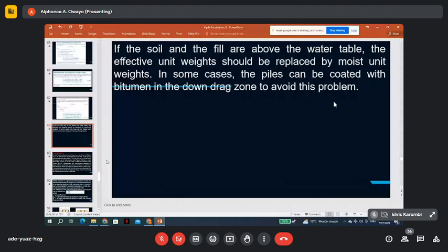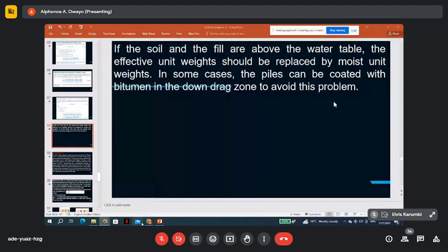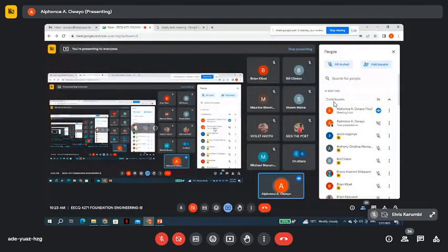So pad footing, if that's not sufficient, you can combine two pad footings, and we already learned how to design all this. You can combine two pad footings in whatever shape. They could be trapezoidal, could be an ordinary rectangle, could be triangular. I'm yet to see that, but it's possible theoretically.